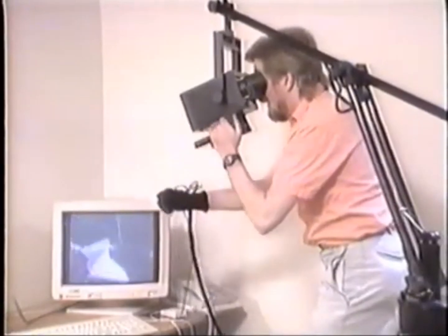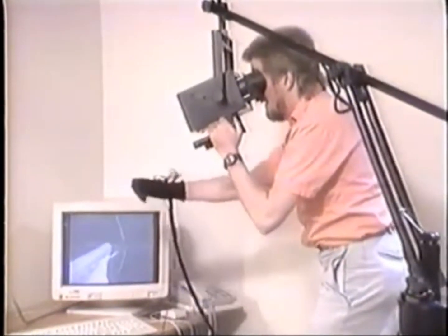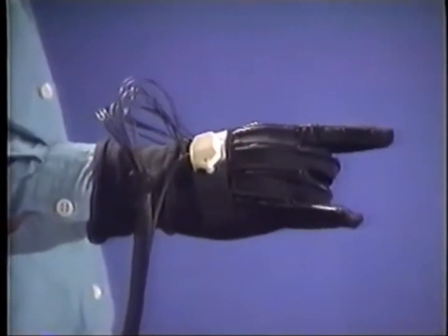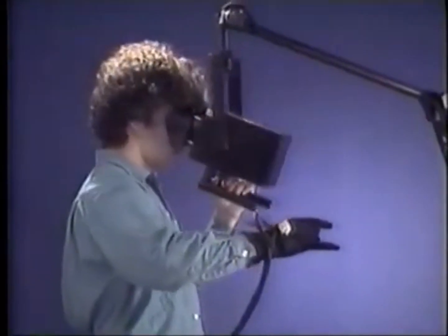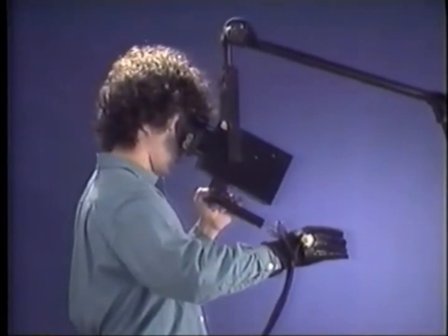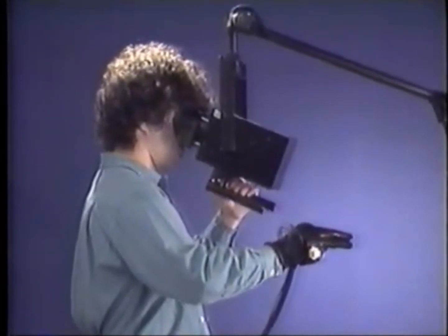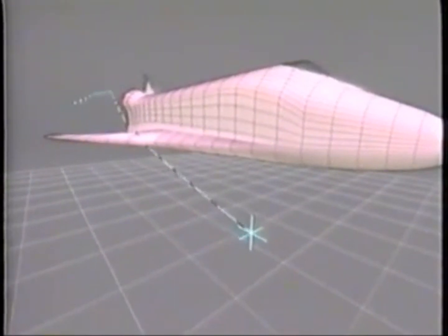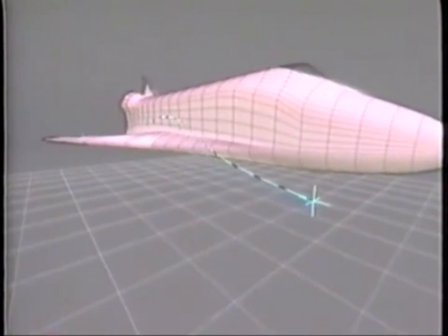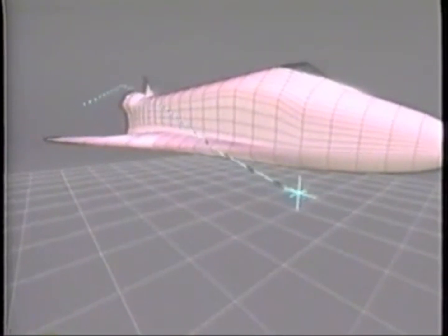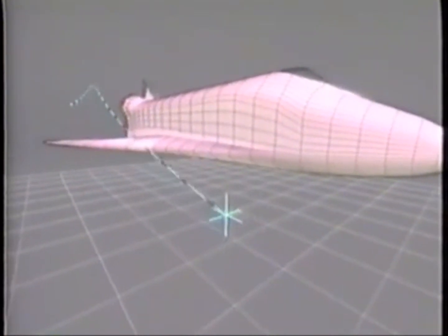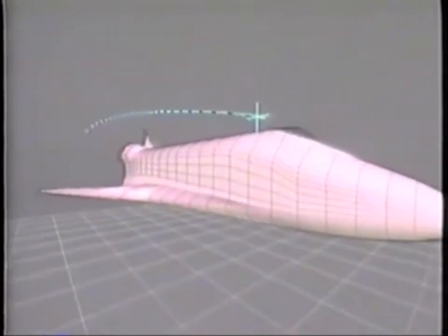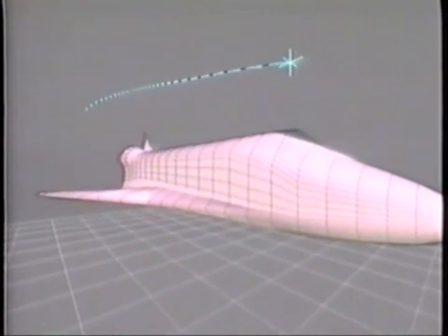Manipulation of the flow visualization tools within the virtual wind tunnel is accomplished by using an instrumented glove. The glove senses the position, orientation, and gesture of the user's hand. A variety of gestures are recognized by the system and are used to control the flow visualization process. A small, cross-shaped cursor tracks the user's hand position inside the virtual wind tunnel. A streamline is computed through the flow starting at the hand position. This represents the path that a particle would travel if it were emitted into the flow. A hand gesture freezes a streamline at the current hand position.